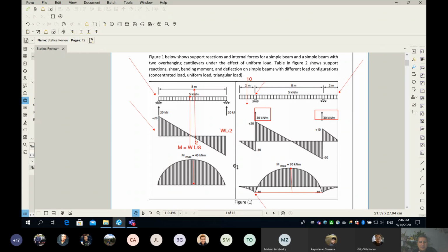if you want to design your beam and you're not really careful about the material, you don't want to save any amount of material, for sure, go ahead, find the maximum bending moment. This will give you the maximum at the center, and we will go ahead and design this whole beam. Let's say the results say we need maybe 5 rebar. What we will do is simply put the rebar all the way from here to there. This means my beam is going to be strong here because it's going to resist the maximum bending moment. But remember, as we go close to the support, what happens?